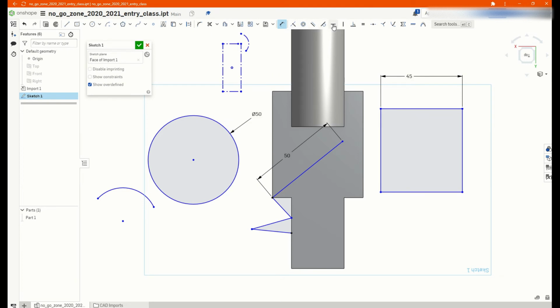And there's a lot of locking tools. These basically lock your geometry features into certain kinds of constraints. So this one is how you put a point on a line. This is how you create 2 circles with the same center point, and this is the parallel line. A lot of these features will come up automatically when you hover over something.